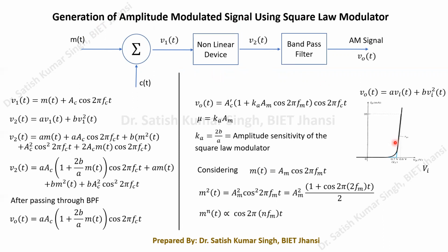If we write the current-voltage equation, the current through the diode is ID equals saturation current I naught times the bracket e to the power V upon eta Vt, minus 1.